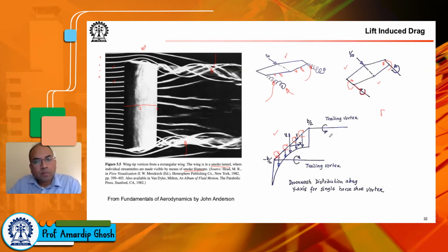So the effect of the wing is really to support a bound vortex, and when you have a bound vortex of a certain strength that satisfies the Kutta condition, of course, when you have a vortex, you have circulation. Now I'm saying that the strength of that circulation or strength of the bound vortex are analogous terms. So the strength of a vortex is given by the circulation developed by the vortex. So the strength of the vortex, or the circulation developed by the vortex, is such that for the wing, the flow leaves the trailing edge smoothly.